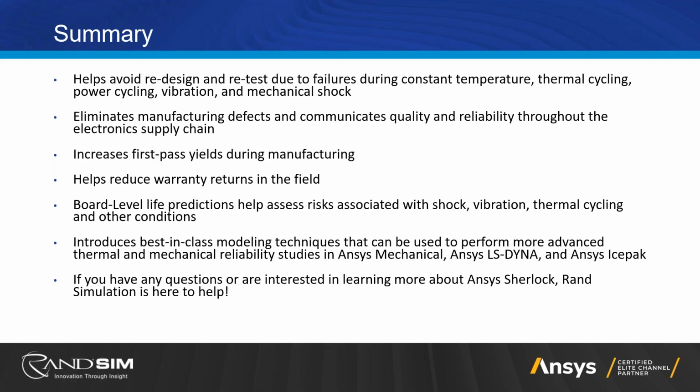It's going to allow you to predict at the board level and assess risks with the different analyses that we mentioned, so shock, vibration, thermal, and some other conditions. And the best-in-class modeling is great. Like that ball grid array example that I was talking about allows you to model it down to the actual solder joint to give you that greater fidelity. And then that links into Ansys Mechanical, LS-DYNA, or IcePak to further build out your reliability analysis.